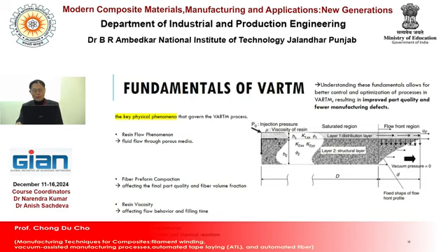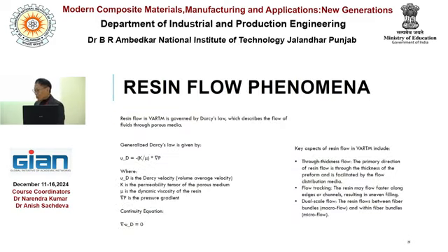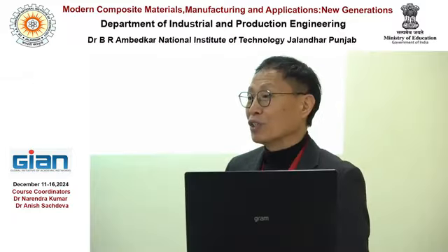Fiber preform compaction affects the final part quality and the fiber volume fraction. Resin viscosity affects flow behavior and filling time. And composite curing behavior is complex heat transfer and chemical reaction. So these four subjects should be calculated in advance by using a computer.